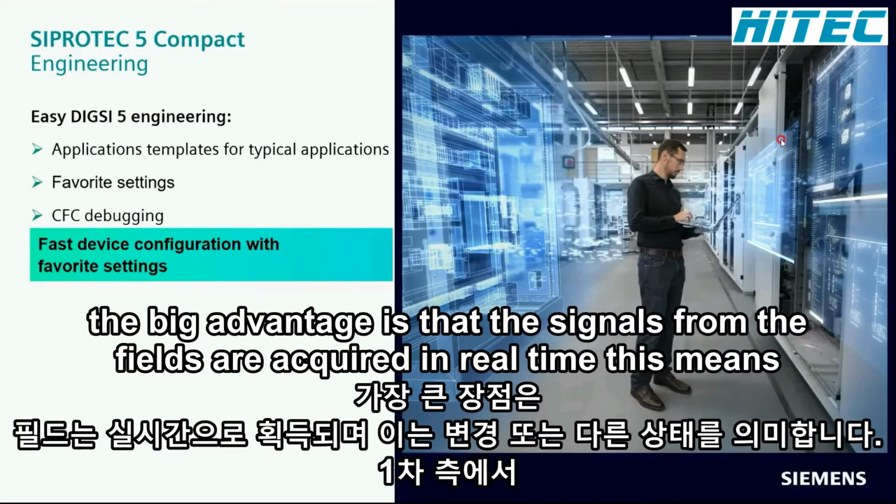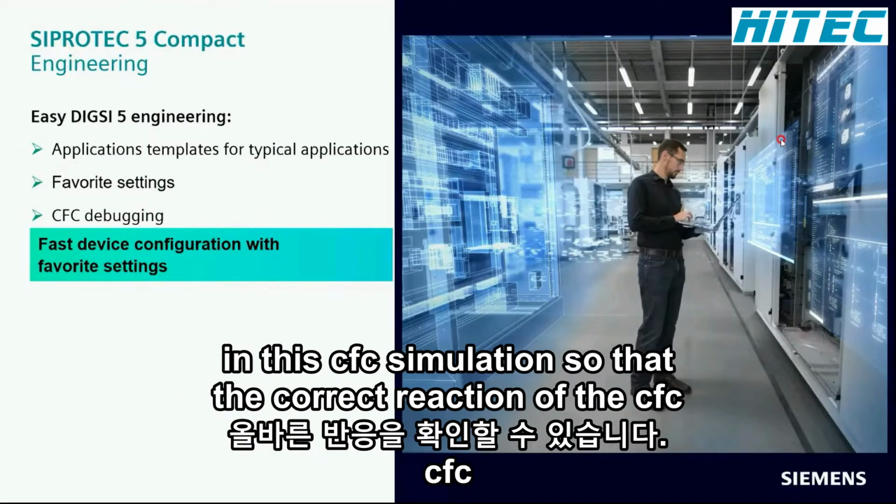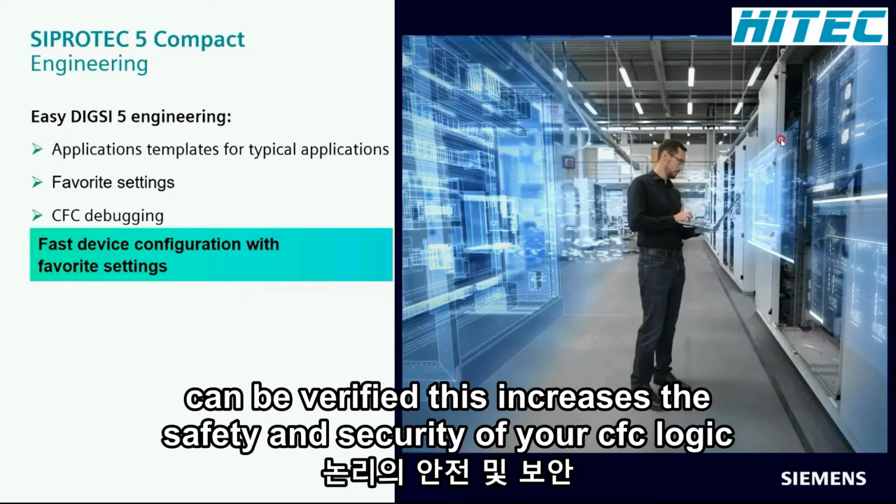The big advantage is that the signals from the field are acquired in real time. This means that changes or different states on the primary side can be traced in this CFC simulation so that the correct reaction of the CFC can be verified. This increases the safety and security of your CFC logic.